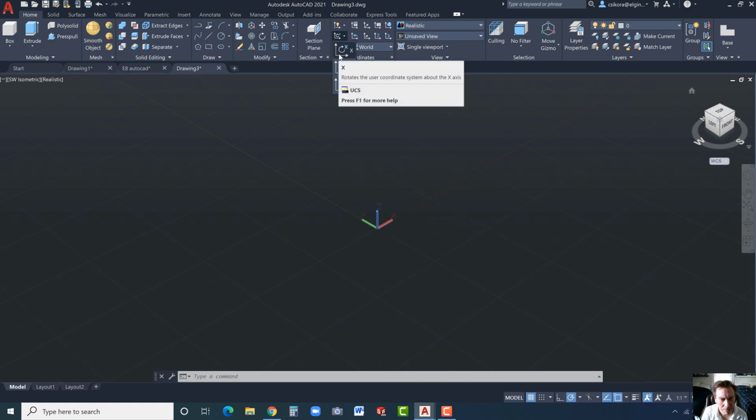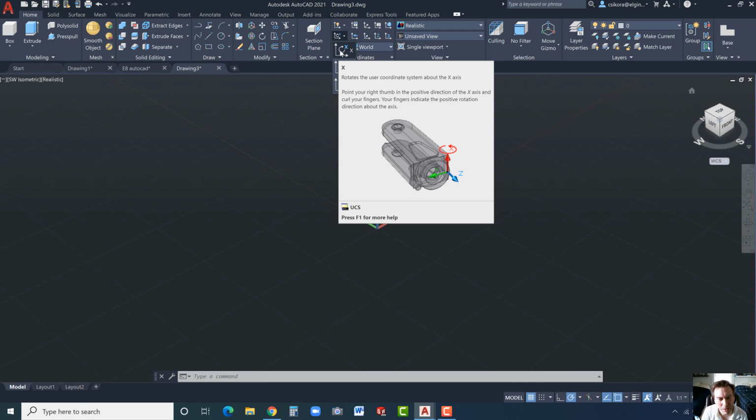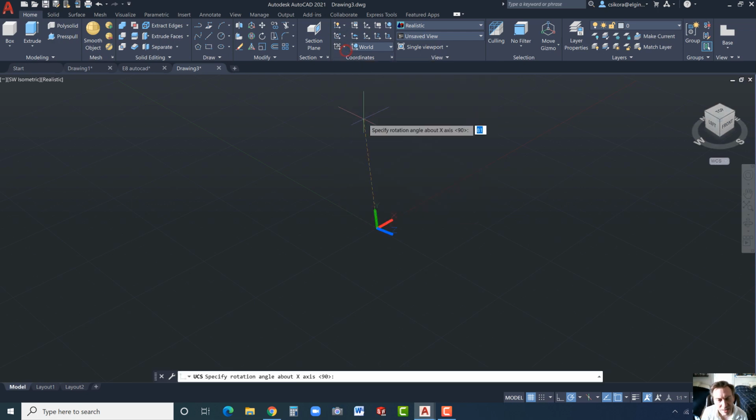So yeah, actually no, we'll have it rotate around the X. Click on the rotate around the X and make sure you drag this straight up, and so the Z is pointing to our right, lower right. Okay, click. Now our plane is off to that side.